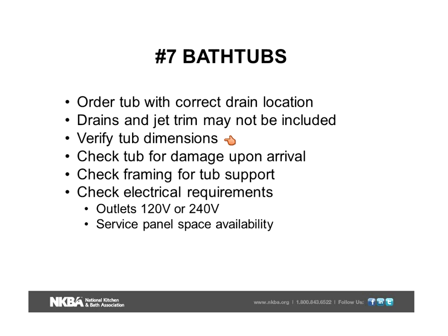Verify the tub dimensions. Now, you and I know that the homeowner is going to measure the outside of the bathtub. Well, the outside of the bathtub is from tile to tile or stone to stone, whatever the wall covering may be. I want to know what the stud to stud dimension is. And generally, it's going to be about 60 inches. And, of course, the bathtub itself, by the time we get the cement board or the old green board on, we've got maybe a 58.5-inch dimension. So make sure that the dimension is accurate because you're going to tear all of that out anyway.